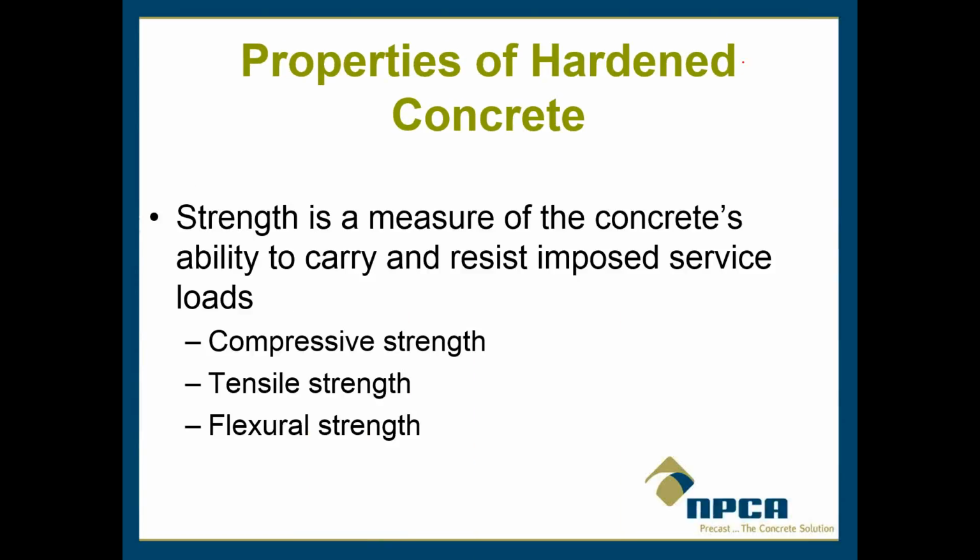Anyway, so strength. The definition is that it's a measure of the concrete's ability or resistance to the loads, the service loads that are applied to it. And concrete strength comes in three forms. It's compressive strength, tensile strength, and flexural strength.